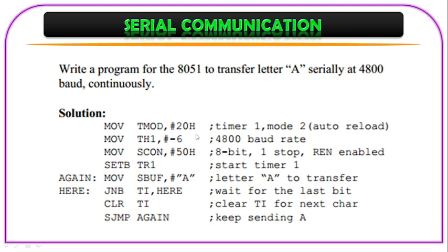It is there in the initial slides. So -6 is loaded into the timer count register, the TH register. It is in auto reload, so you will load only the timer higher order register. And then the serial control register is loaded with 50H for mode 1 of serial communication. And then start the timer, so set bit TR1 for starting the timer.